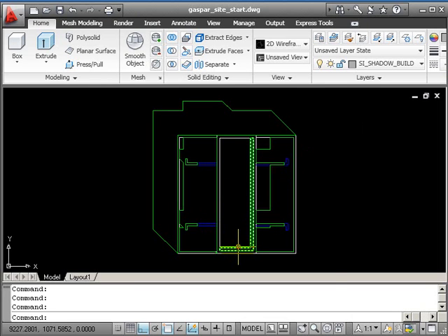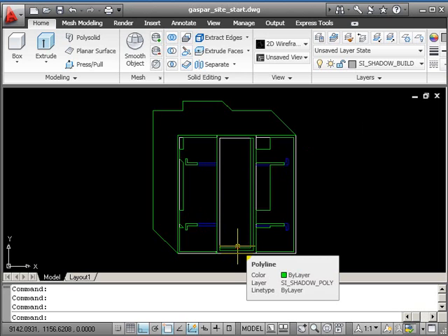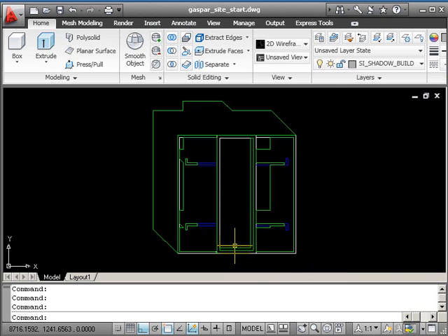Okay, what you want to avoid with hatching is trying to do all the hatching at the same time. If you do that, they all become one big hatch object, and if you decide to modify something, it's difficult to unpick a bit of hatch from the rest of it. So you're probably best to do your hatching in 5 bits. 1, 2, 3, 4. 4 bits actually. 4 areas of shading. So if we do hatch, it's H-A-T-C-H.